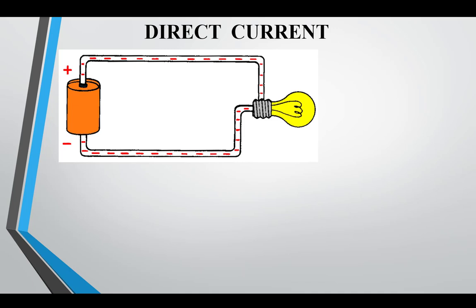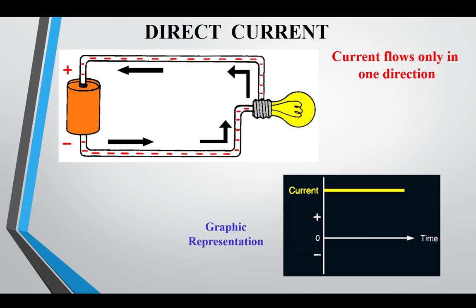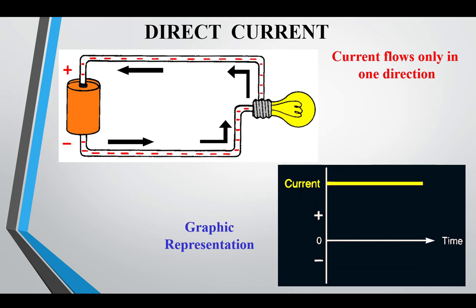So when we talk about direct current, we're talking about directional current. The current flows in only one direction, as we're being shown in this circuit. And if you look at the current over a period of time, we see a graph here, the current's at a certain level, I don't know, 3 amps we'll say, and if you start the stopwatch at 0.0 here, then as time goes on, this current maintains a certain magnitude, but more importantly, it maintains a certain direction of flow. It never flows the opposite way.